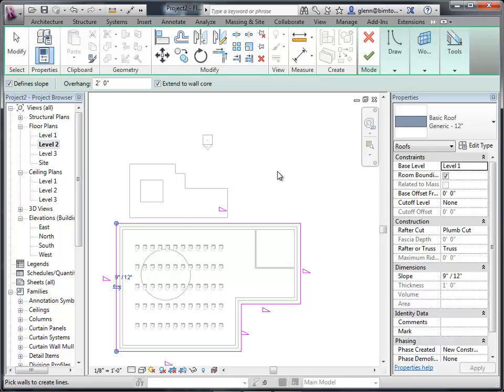Okay. A 9-12 roof is a roof that says either I have a lot of slope or snow that I need to shed, or I have a big important house and I want you to notice it when you drive down the street. Really, A-frames are taller than that, but very steep roofs we tend not to build as much anymore unless you're making a statement house.